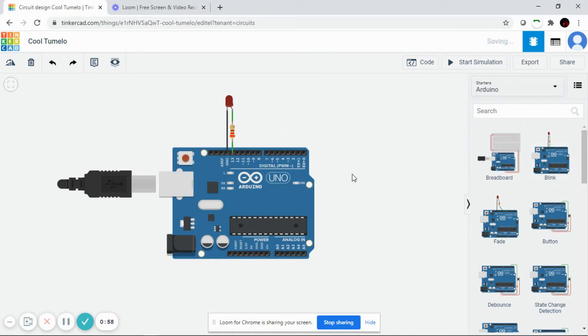Okay, there you go. First of all, we can notice that the LED's anode is connected with a resistor to the pin 13 of the Arduino, and its cathode is connected to ground. Why do we use a resistor? Normally, LEDs have a forward voltage which lies between 1.8 volt and 3.3 volt, and the Arduino pins will produce an output voltage of 5 volt. If we connect a normal LED directly to a 5 volt source, it will glow for a while, but then it would eventually die off or start emitting smoke.